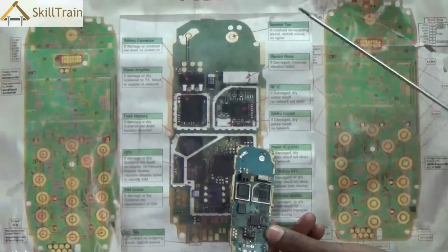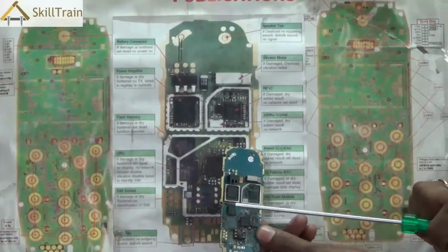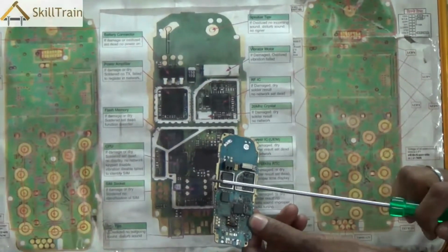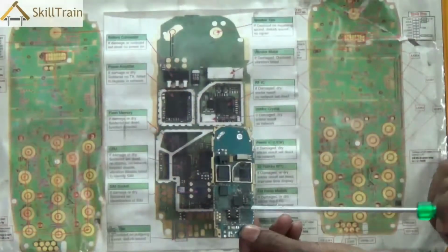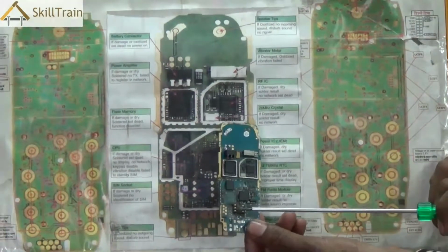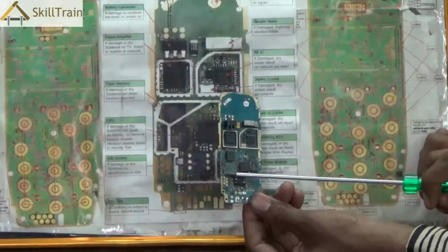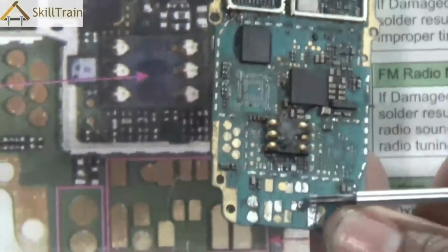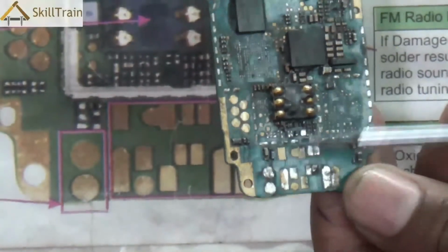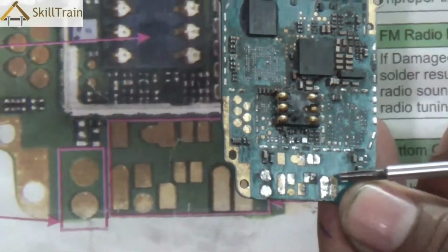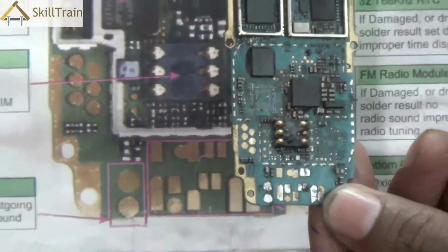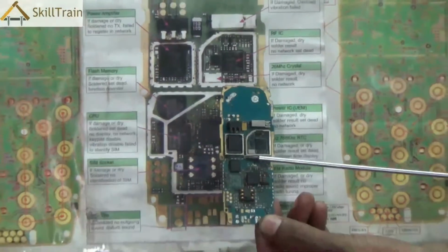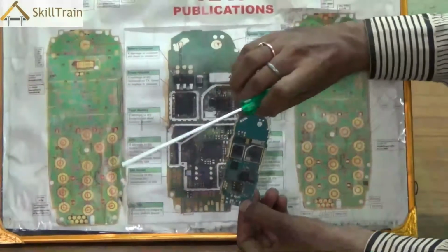The CPU is placed in this position, but we have removed it now for some practice purposes, where the CPU is placed in that position where it is empty right now. Underneath that is the SIM tray where the SIM card is placed. Right next to that is the software tip where you can connect to flash software. Underneath are several other tips including for the headphone, mic, hands-free charging tip and data connector tip. So, this is how a typical PCB looks like for any mobile phone.